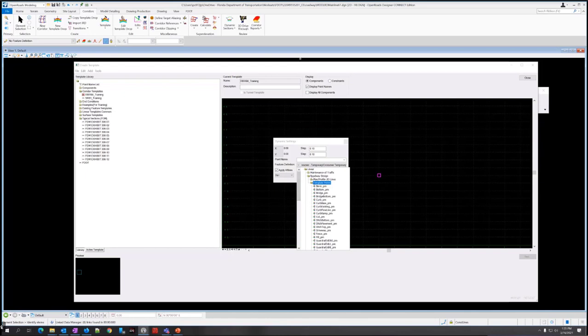So go under linear, then under roadway design, and then under template points. And there's all the ones that say underscore PM. Those are the proposed PM and this proposed model. So we want to go to template miscellaneous underscore PM. Select that option. And then let's uncheck the Apply Affixes. These are the affixes, the LT and RT that we just set up. Right now we're not going to use it, but it's set up in the preferences. So whenever we need it, we just come back here and turn it back on.